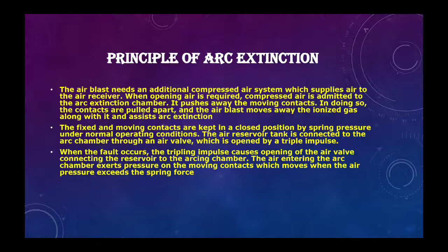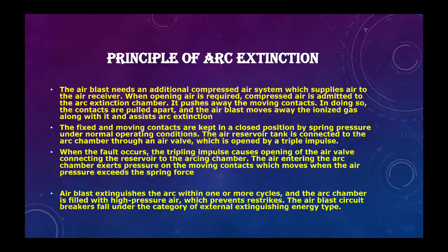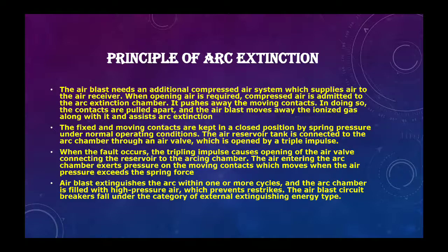and the air entering the arc chamber exerts pressure on the moving contact, which moves when the air pressure exceeds the spring force. An air blast extinguishes the arc within one or more cycles, and the arc chamber is filled with high pressure air which prevents restrikes.